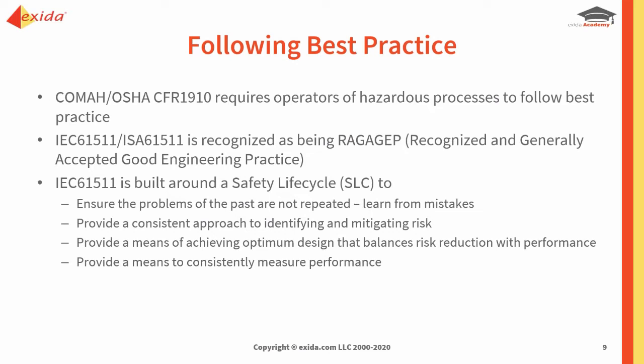61511 is built around the safety life cycle. So effectively, there are 3 stages. There's an analysis stage where we have to assess and analyze where our risks are according to our hazards and what the consequences of those hazards are, and therefore what we need to do in terms of defense mechanisms to be able to reduce those hazards to an acceptable level.